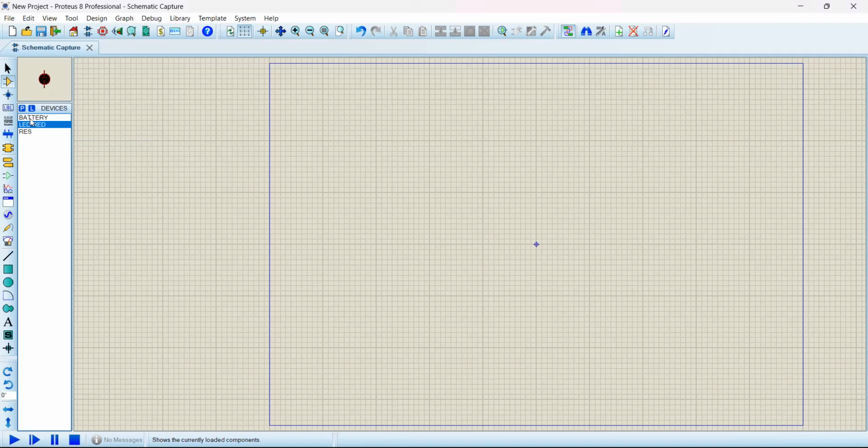Now I will have to connect. If you want to take your component from this section inside the box, remember the inside of the box is where we connect. You click on that component. Now I've clicked on the battery. You can see by this blue color that my battery is selected. You don't press and hold the mouse and go to the box.